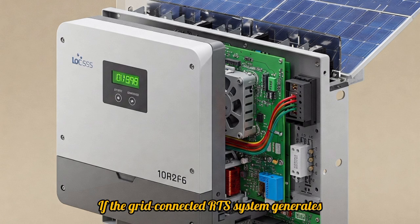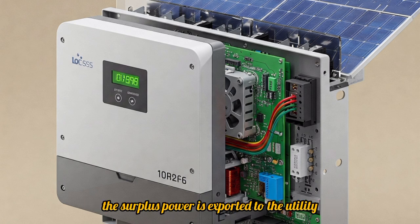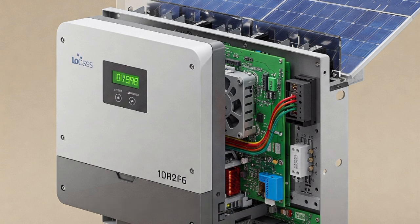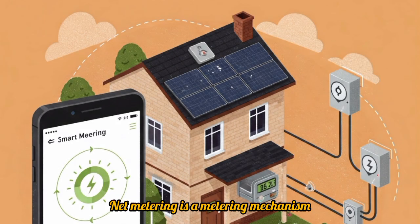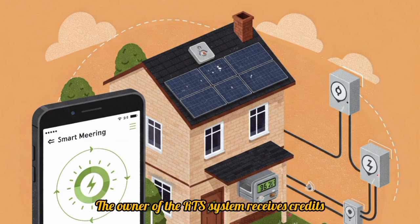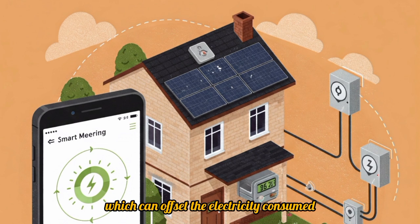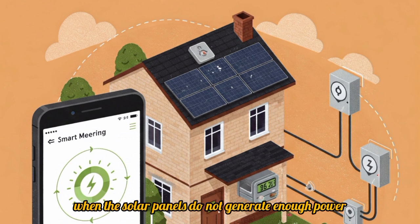If the grid-connected RTS system generates more electricity than is consumed by the building, the surplus power is exported to the utility grid through net metering. Net metering is a metering mechanism which allows for the measurement of both electricity imported from the grid and electricity exported to the grid. The owner of the RTS system receives credits for the excess electricity exported, which can offset the electricity consumed from the grid during times when the solar panels do not generate enough power.